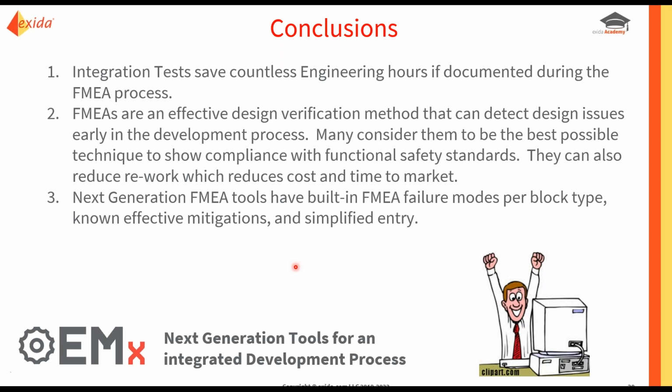you may find a particular design flaw that will be easy to rectify digitally in your ECAD program, whether it's Altium or whatever program you're using, instead of getting to the point where you've manufactured a few prototypes. Then not only do you have to go back and change your design digitally, but you also have to do another rerun of your PCBs. And then next generation FMEA tools have built-in failure modes per block type and known effective mitigations, and this leads to simplified entry.